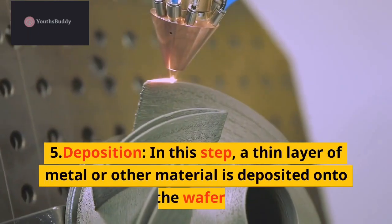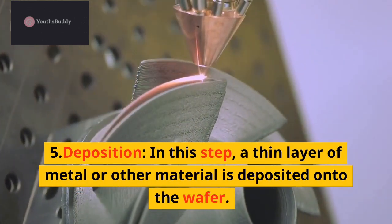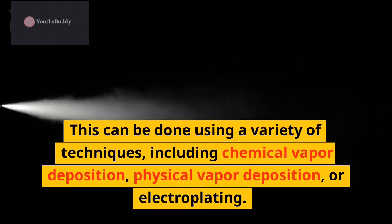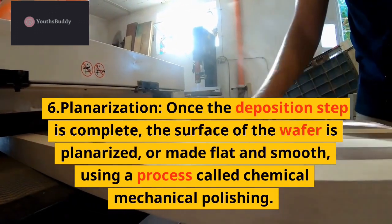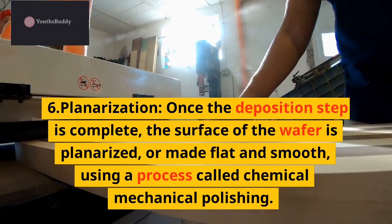5. Deposition. In this step, a thin layer of metal or other material is deposited onto the wafer. This can be done using a variety of techniques, including chemical vapor deposition, physical vapor deposition, or electroplating. 6. Planarization. Once the deposition step is complete, the surface of the wafer is planarized, or made flat and smooth, using a process called chemical mechanical polishing.